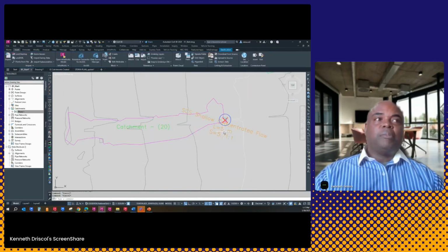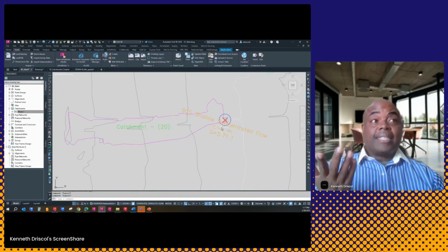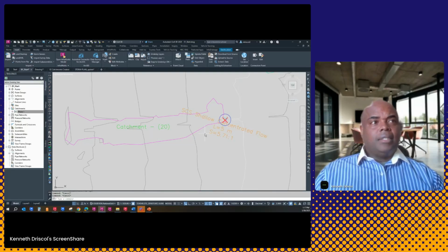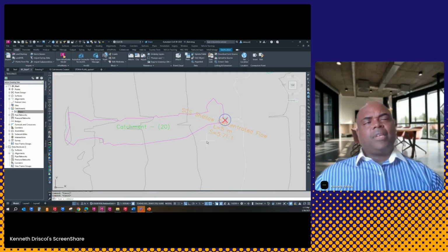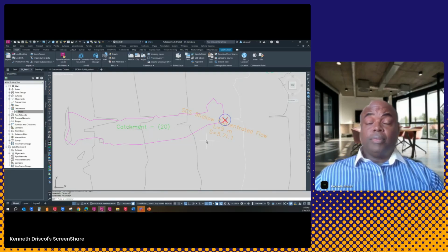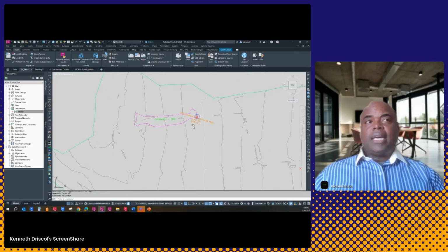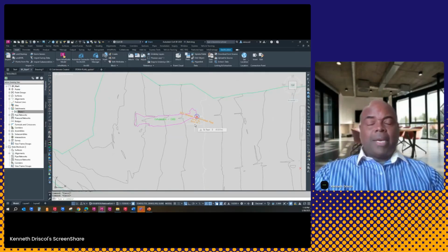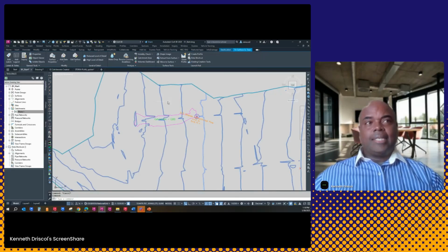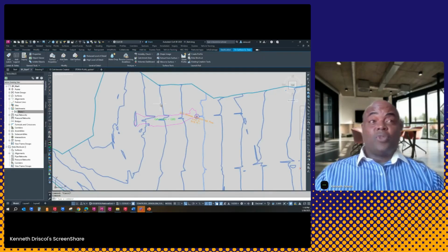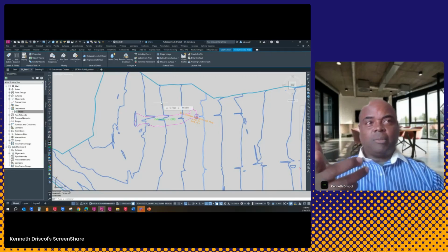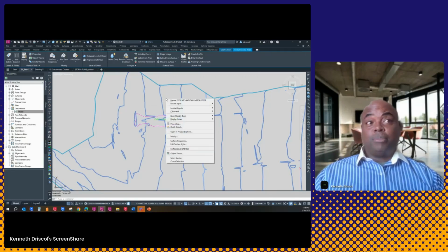But a simple label. But if we look at this distance, we say, wait a minute. Now it calculates the slope and the distance, but depending on the length, that would be something to be desired. One of the things that I always look at in terms of my existing ground surface is my topo and where water is draining to, because ultimately we need to determine how to get water to a certain point.